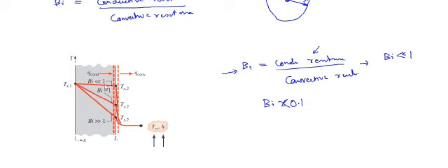small. Now if you look at this picture, you can see when the Biot number is very small, the temperature gradient, the difference between temperature Ts1 and Ts2, is very small. The line is almost parallel, but there is a small inclination that should be there, otherwise there won't be heat transfer. And when it is equal to 1, you see that the temperature gradient is much steeper. When it is greater than 1, the temperature gradient is even steeper.